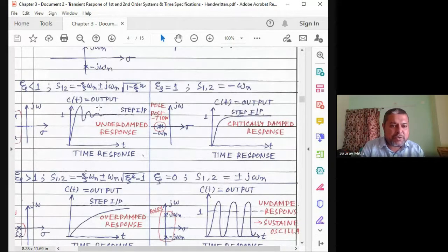After a certain time, this part is called the transient time. From the initial instant up to this time is called the transient time. You don't find steady state error in transient time. You first let the waveform become stable and come to steady state. The waveform has come to steady state here after this time. Now this is the output and this is the input, and we look at the difference between them. It is not necessary that the steady state response will be the same as the input. It can be undulating and it can reach steady state here, let's say at 0.6 volt.